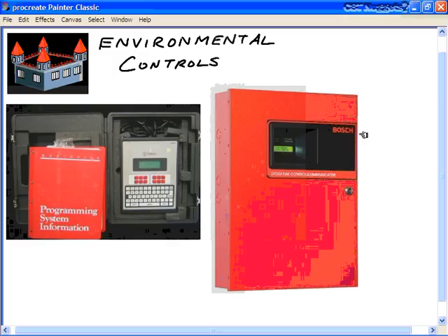These are alarms that are accessible to the fire department. They should be weatherproof. They should be in a controlled room with access prevented to unauthorized personnel. They may be on dedicated or separate circuits. They have to control or disable certain zones within your facilities, your organization. They also have to adhere to local and national regulations.